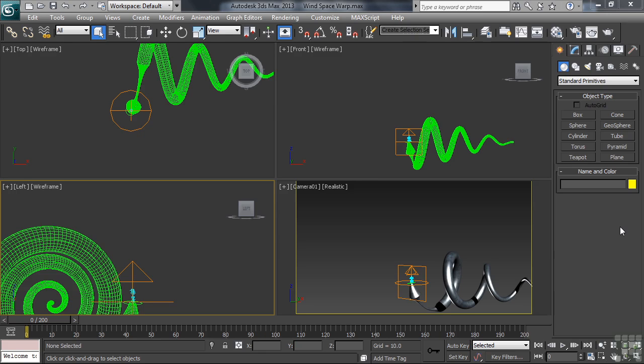In a nutshell, a space warp can be defined as a non-rendering object that's used to affect the appearance or behavior of something else in a scene. They can be used to create a wide variety of effects, from object-deforming space warps capable of creating things like waves and ripples on a 3D surface, to force-like space warps used in a scene to generate atmospheric effects like wind and gravity. There's even a special subset of space warps that are designed to be used as deflectors, having particles pointing in the direction of the space warp bounce or deflect off that space warp surface.